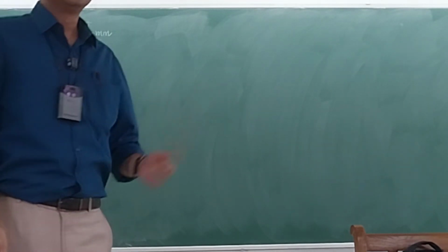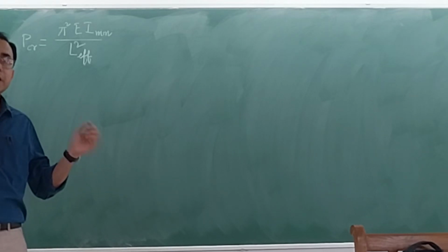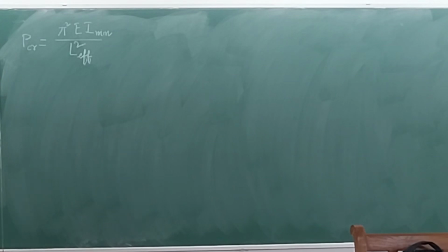So if you look at the tutorial sheet, you'll find a number of problems where this difference in the I has to be carefully taken care of. Okay, all right. Now we want to do something special with this. We have the P critical. Now, what we'll do is we will try to reconsider this not in terms of the force, but in terms of the stresses induced.